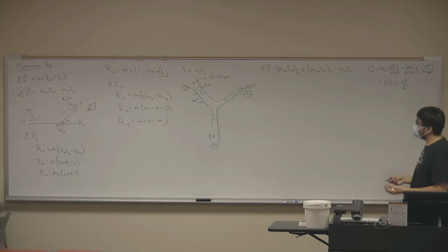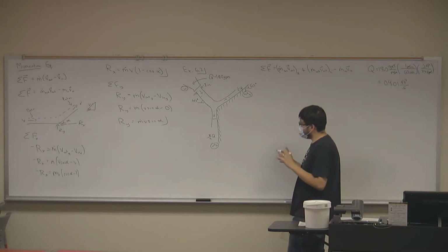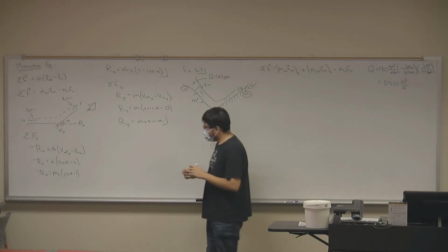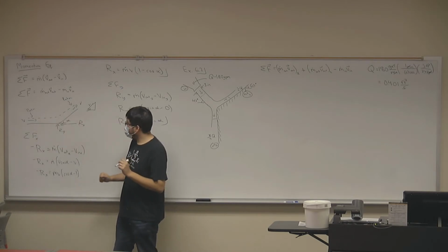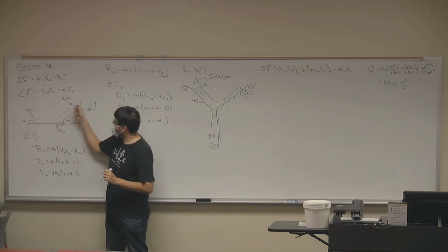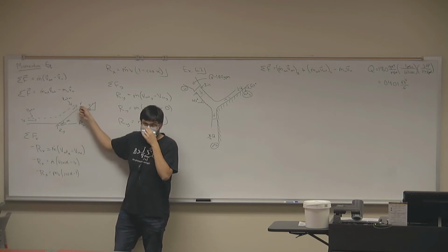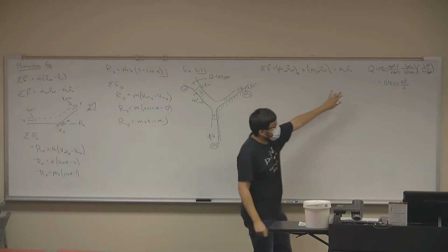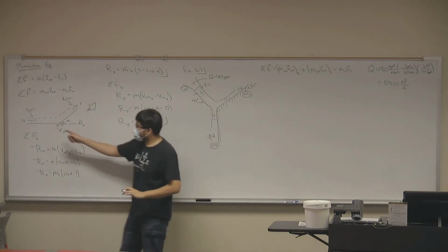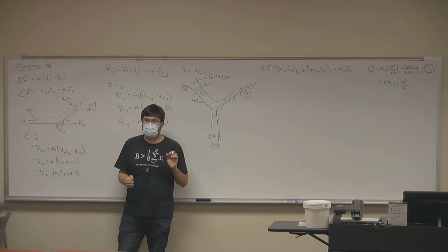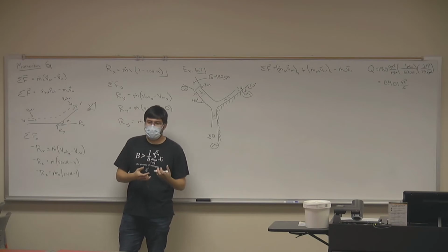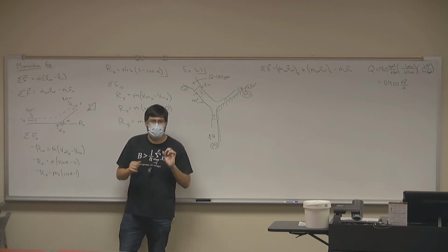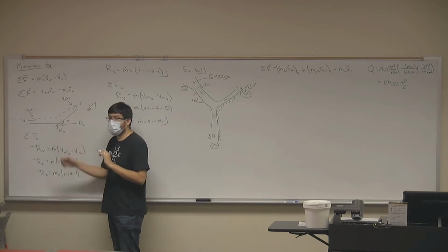Now, when it comes to velocities, however, we can be a little bit more generous, because notice that our deflector theory shows us that the velocity magnitude remains constant. So even though flow rate may change, the magnitude of the velocity should remain constant through a deflector. Of course, if flow rate changes but velocity doesn't, then area needs to change. But we're not going to look at area for now. For now, let's focus on these velocity terms.